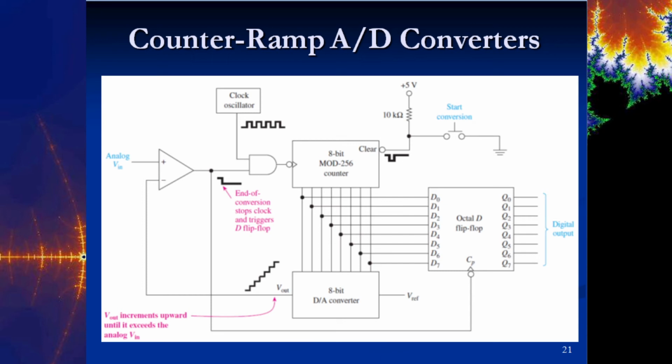Okay, so again, this will go low briefly. This is a negative edge trigger flip-flop, so wherever the D was here, these inputs get passed through. Remember, Q follows D with the D flip-flop. So when this activates on the negative edge, it's going to pull all these through to this digital output, and then it gets sent somewhere.